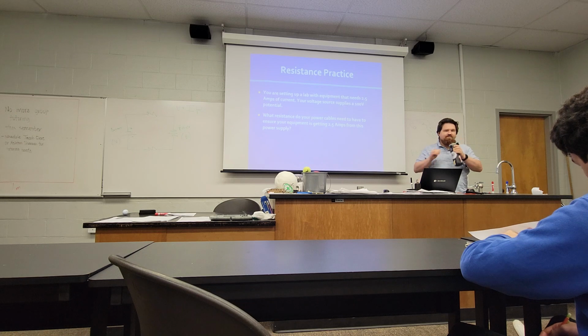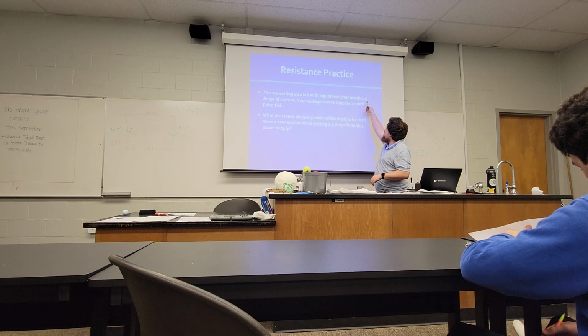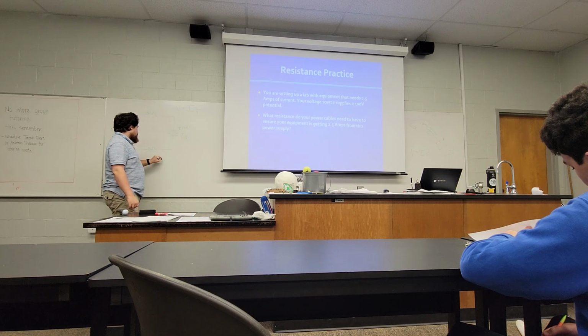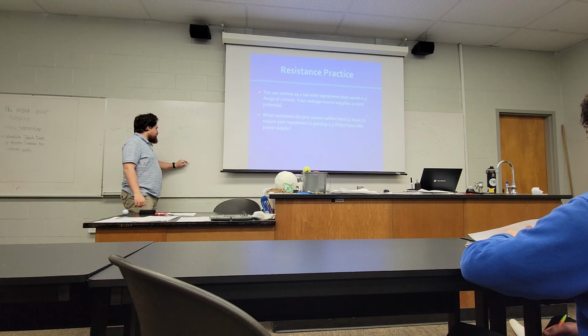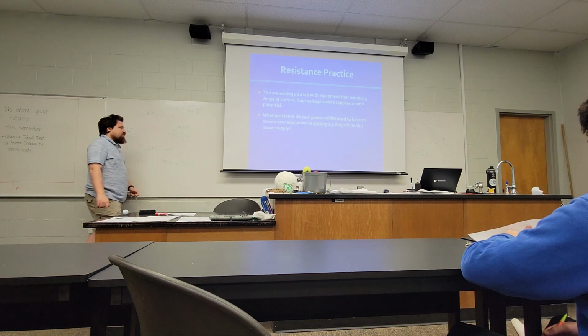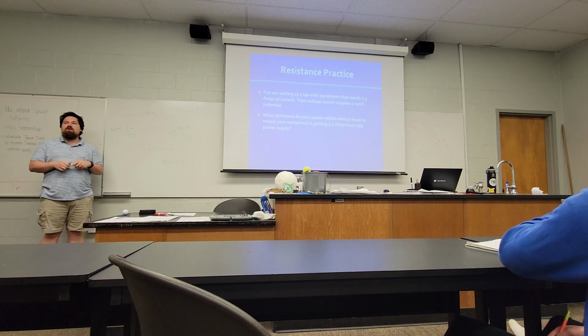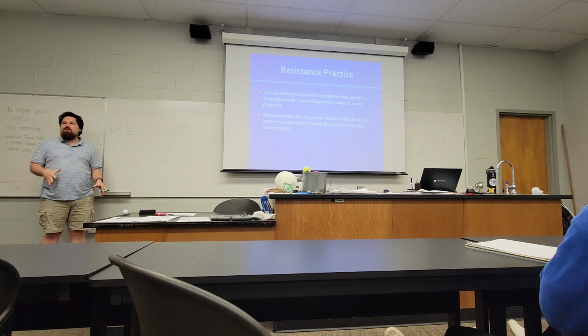Ready? 40, precisely. We've got 100 volts, that's V, 2.5 amps, that's I. V equals IR, therefore 100 equals 2.5 times R. That R is going to be the needed resistance of our system so that the 100 volts is pushing 2.5 amps through it.